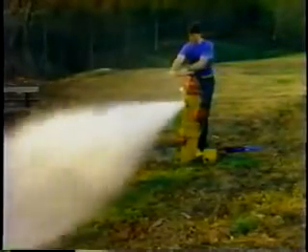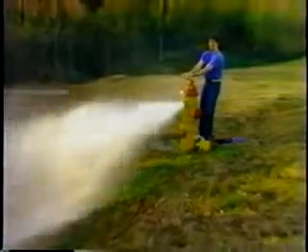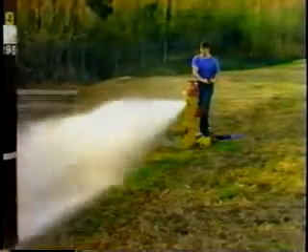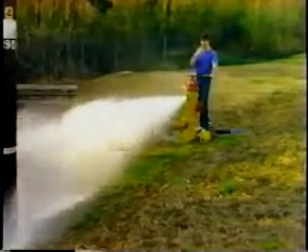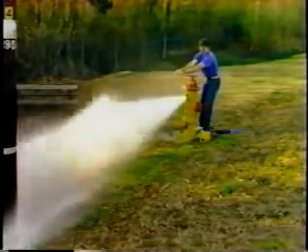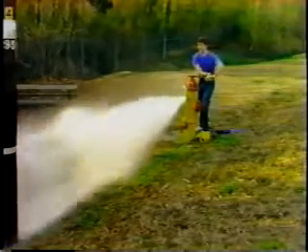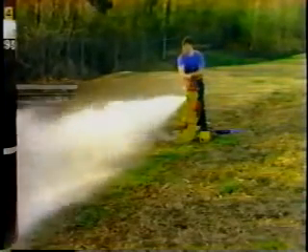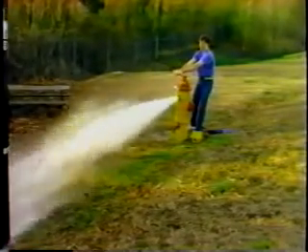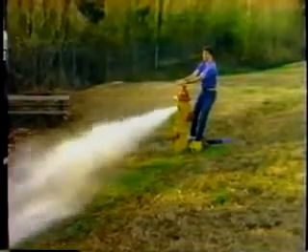Remember, when you're removing a cap gauge from a hydrant, that if the hydrant's still pressurized, that gauge can fly off and cause a lot of damage. So always look at the face of the gauge to make sure there's no pressure on the gauge when you're removing it. Also, a flowed hydrant can cause flooding damage. Please be considerate of your neighbors. And water hammer caused by quickly shutting off a hydrant can damage the distribution system. So the thing to remember when you're doing this type of work is be careful and be safe.